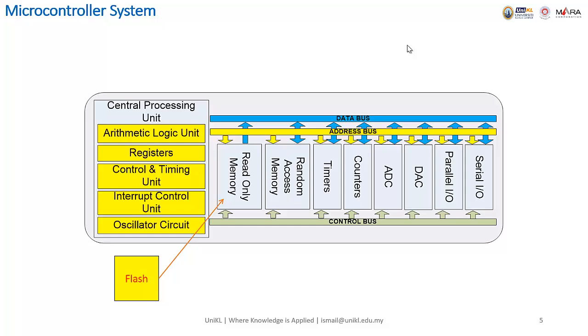Then comes another one that we call the EEPROM, double E: electrically erasable programmable read-only memory. Now we can erase it by using a device that we call a programmer. Just place it on the programmer, select the ROM or the device that we use, and then we can delete it and write the code into the program. But whatever it is, it still takes time.